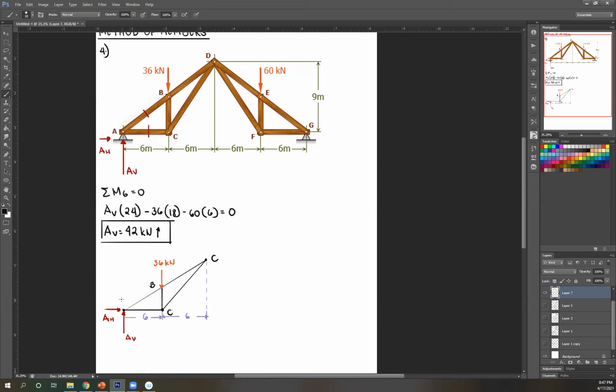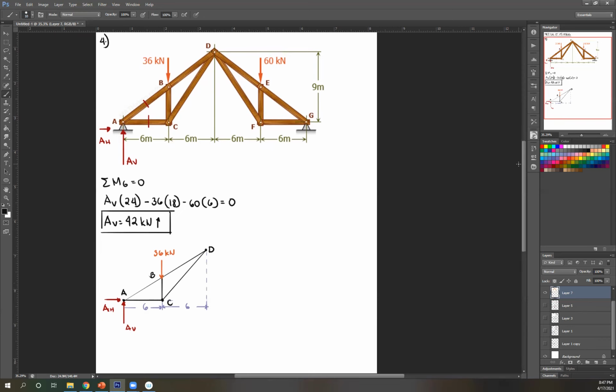So I've successfully isolated that. Again, this is A, B, C, D. Right. What's the goal again? Getting AH. Now I can get that by using this free body diagram. Remember, you can take moment about any support, any hinge, any connection. I have a hinge at D, so therefore I can take moment at D.